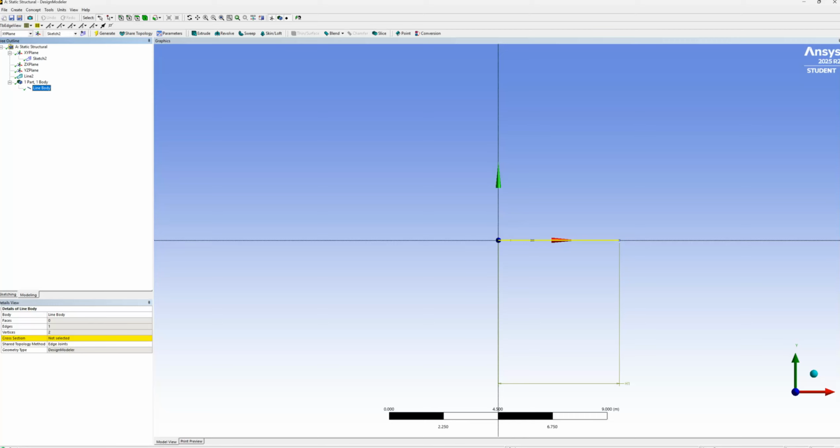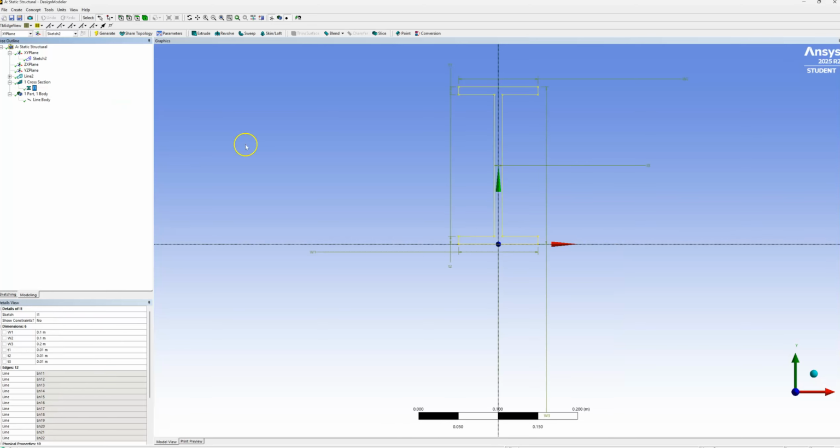So in this particular instance, we're going to use an I-beam cross section. When you go into concept and you look at cross sections, there are numerous different types of cross sections. I section is what we will do. If you wanted your own specific cross section, you can also draw it using this user defined option here. But for the moment, we will just use the I section. When it pops up, you will see there are various dimensions for flanges and webs.